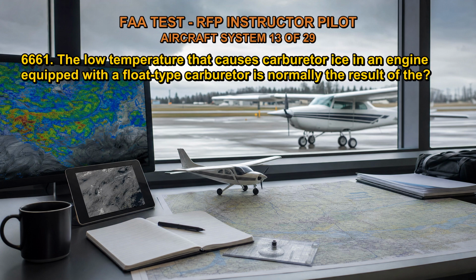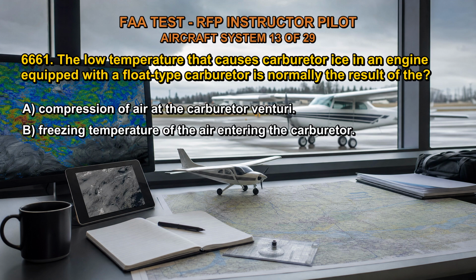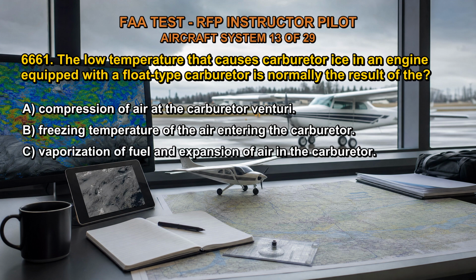6661. The low temperature that causes carburetor ice in an engine equipped with a float-type carburetor is normally the result of the: A. Compression of air at the carburetor venturi. B. Freezing temperature of the air entering the carburetor. C. Vaporization of fuel and expansion of air in the carburetor. The correct answer is C.